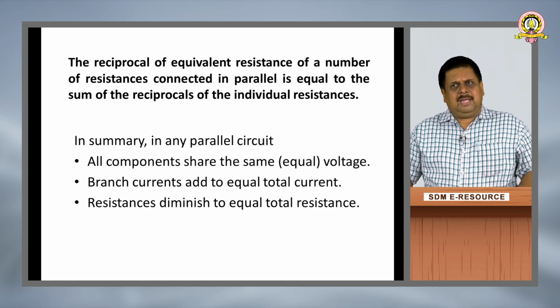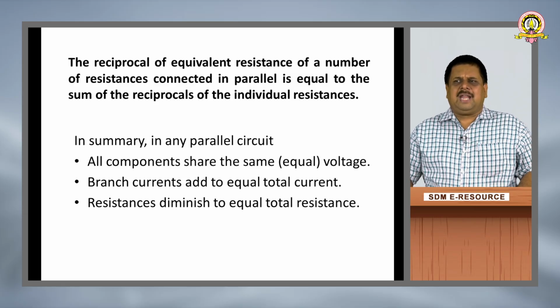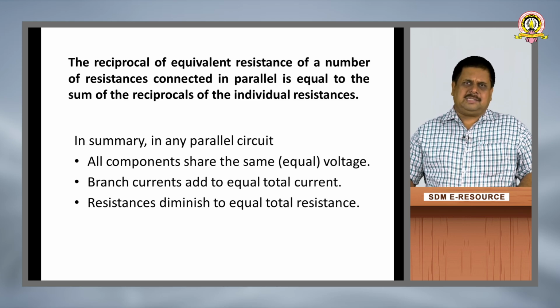In summary, in any parallel circuit, all components share the same voltage, branch currents add to equal total current, resistances diminish to equal total resistance.